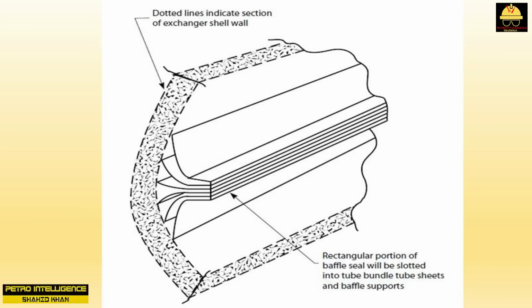Also, unless great care is taken by maintenance personnel when installing the new or replacement longitudinal baffle sealing strips, the heat transfer efficiency of the exchanger will be greatly reduced after it is returned to service. As a result of this deficiency, most operating companies severely restrict the use of 2-pass shell-side heat exchangers.